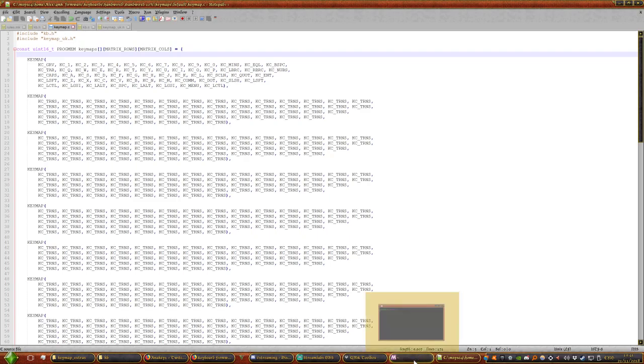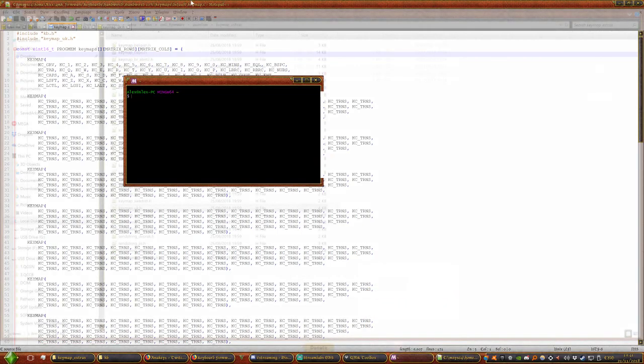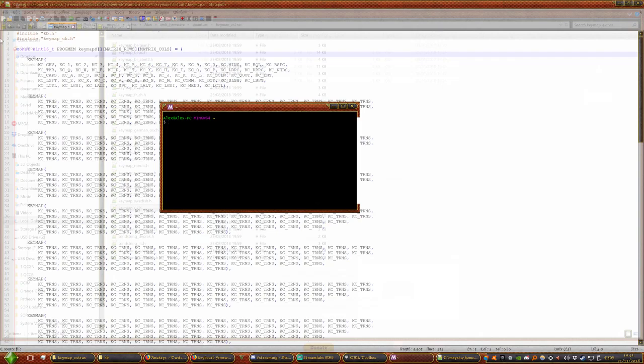And now we're going to compile. This is basically like a Linux style editor. First of all, we need to go into the QMK firmware folder, so we'll just change directory into there. I've been making a board called RS Cherry, which is for one of the vintage keyboards. So we now want to make in handwire, handwire 60%. And then hopefully this should make your build file.